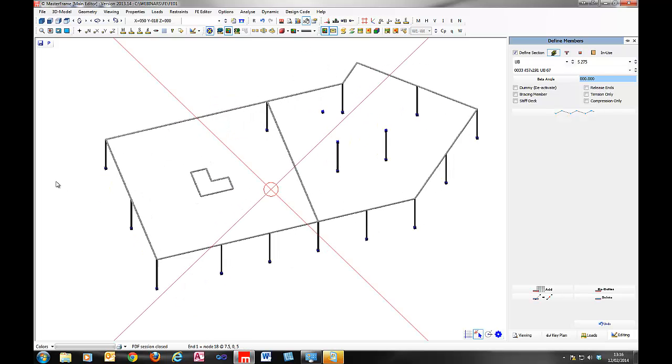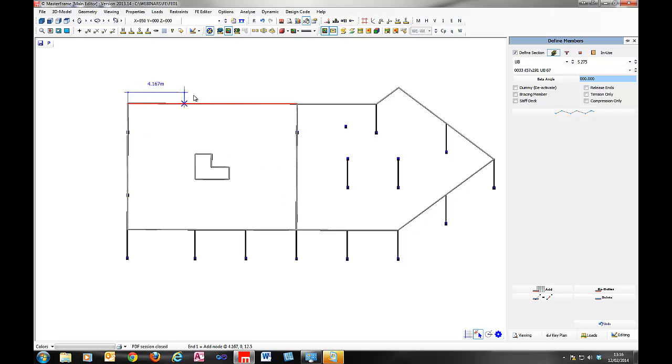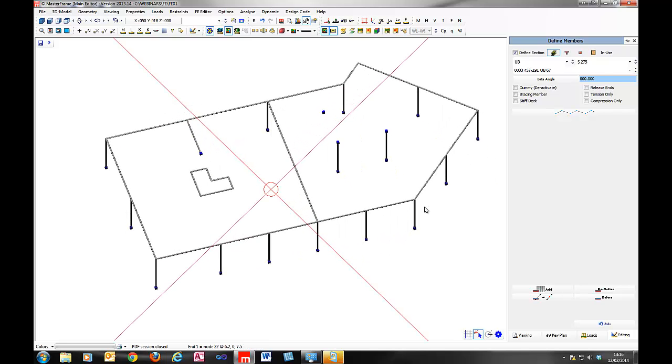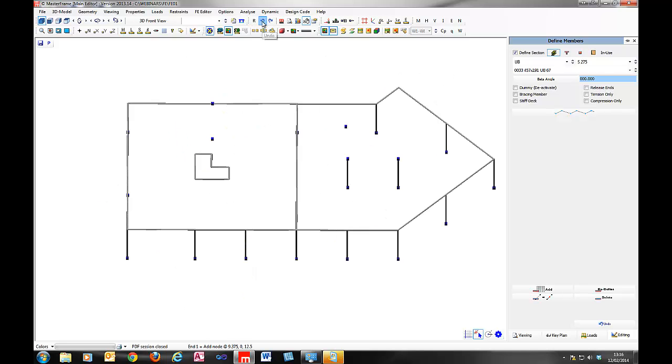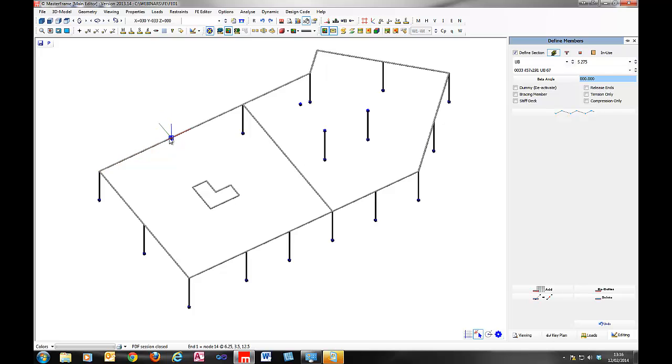And finally, I think I'll just have a mid column up here, so there isn't any regularity so much to our columns at all. Oh, I accidentally was moving in the wrong direction there, so I'll just do a quick undo. And this is where it's useful to have your view in such a way so that you aren't ambiguous in terms of the direction you're moving. And let's go 3.5, and going out this direction, have a temporary tracking point there to create a little system of members